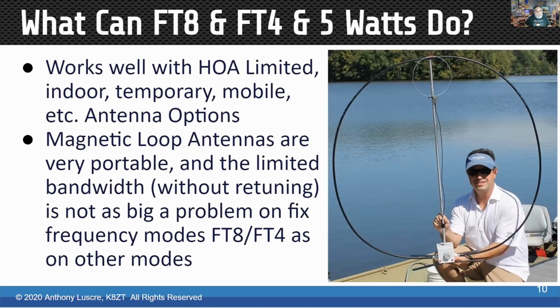If some of you have antenna restrictions, FT8 is a weak signal mode, and you can make contact with antennas that you don't normally have a lot of success with on single sideband, and so balcony antennas and things of that nature. Mag-mount antennas, magnetic loop antennas work pretty well, but the problem when you're using them on single sideband or CW is every time you QSY and move your frequency a little bit, you've got to tweak it again. Well, with FT8 and FT4, once you get to the band you want to operate in and get everything tuned in, you don't touch the dial again, so they're a great combination for FT8 and FT4.